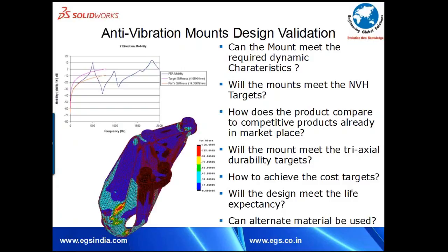The most intrinsic part of an anti-vibration solution to any customer is a mount design. The product may perform, but if the mount is not able to withstand the energy and it transfers the energy over to the product, it is bound to fail on account of the mount. So every one of the mounts that you see on, let us say, a vehicle is designed for a particular life.